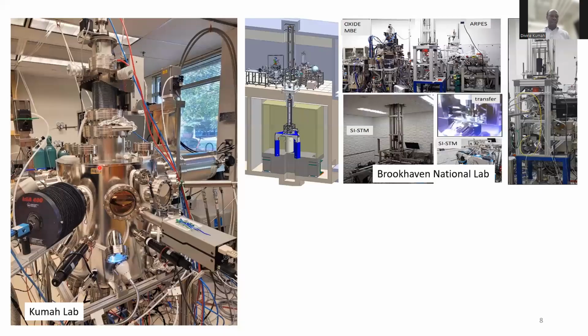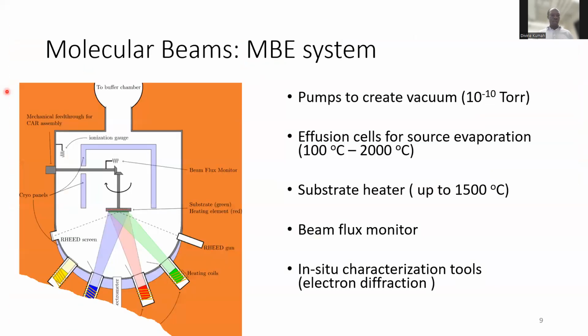And so going back to the picture I have here, the substrate manipulator is this whole system here, which extends into the MBE system. And it sits on bellows, which allows you to move your sample in X and Y to get it centered, but also to rotate it during the growth so that you get a uniform deposition of your thin film, right? So this whole system here allows you to rotate your substrate as you grow.